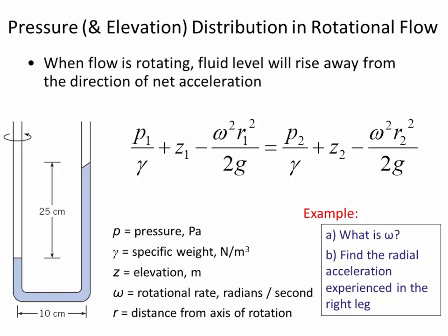Finally, what other variables are there in the equation? Well, g, so easy, we usually don't write it, except when you unexpectedly switch into traditional units and start writing 9.81 when it should be 32.2. The way to avoid that, of course, is to always write the units in every step of the calculation. Then when you write 32.2 feet per second squared, you'll see there's a mismatch. You'll figure out your own mistake if you always include the units.